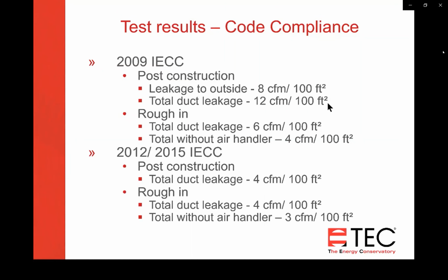At rough-in, total duct leakage 4 CFM per 100 square feet of floor area, so it's the same whether you test it at rough-in or you test it with the sheetrock on. The target is the same. If you test it without an air handler, the requirement is 3 CFM per 100 square feet of floor area.